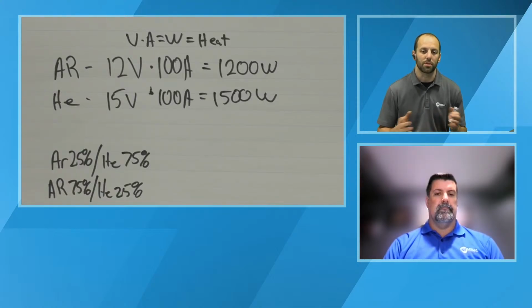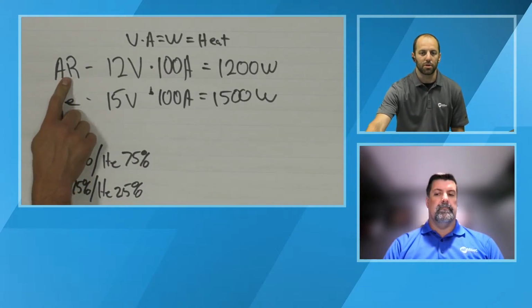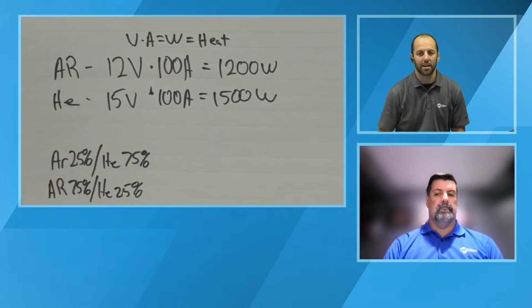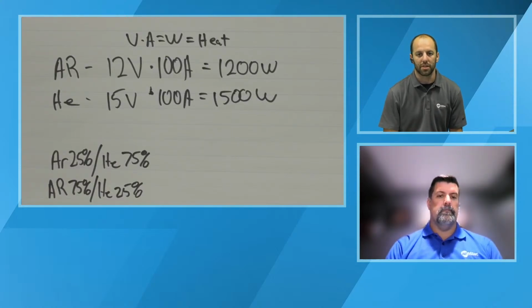So last week we talked about tungsten and using the right size tungsten to get the arc started consistently. Same thing applies here: if we are using an argon gas, it's easier to ionize that gas and get that arc lit. With helium, we're probably going to need to make some adjustments in that general setting that we referenced in last week's live stream.